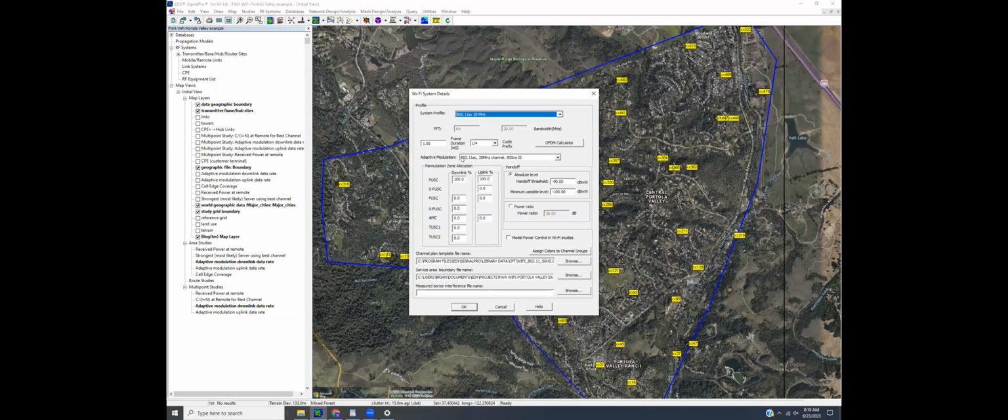And I also select an adaptive modulation chart here, which basically correlates the signal to noise ratio that you need to reach each coding level, each modulation type, and then what the deliverable data rate would be for each of those different modulation types. And of course, we keep track of that on the uplink and the downlink.